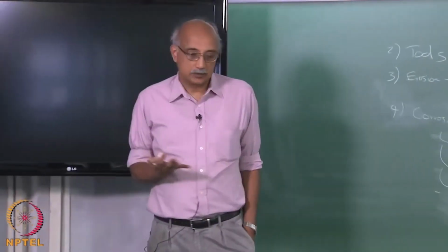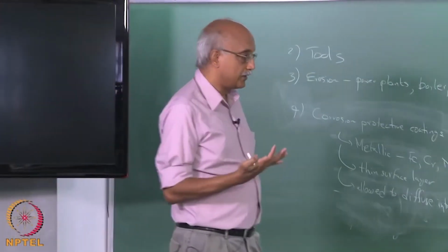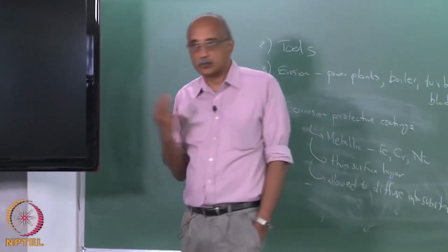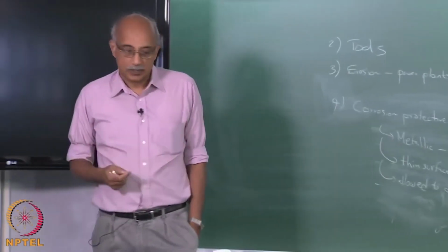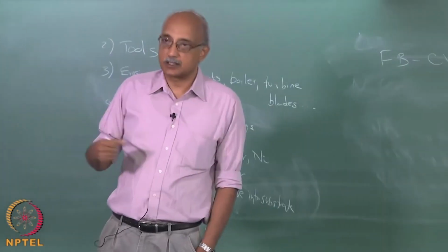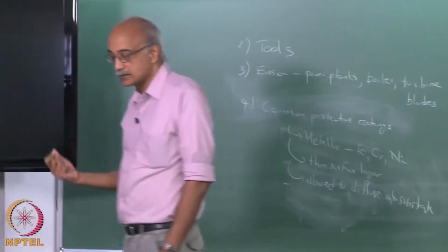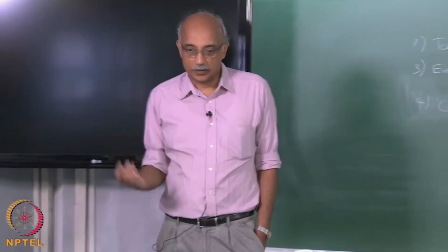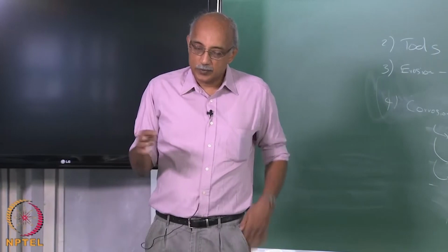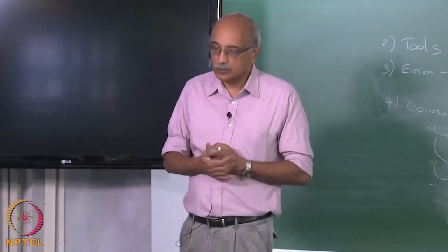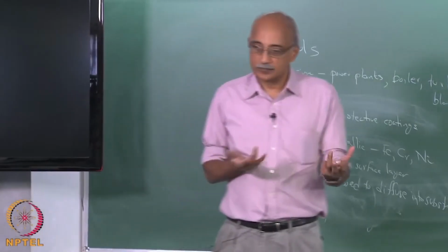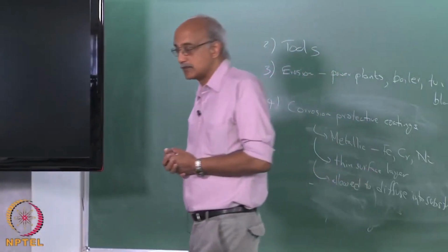So, you fluidize it again using a carrier gas that may be inert gas, or it could be hydrogen, or it could be nitrogen, and along with the carrier gas you also introduce certain reactive species such as chlorine or HCl or HF and so on, and then you essentially prepare this bed and you fluidize it using this mixture of carrier gas, inert gas and the reactive gases.